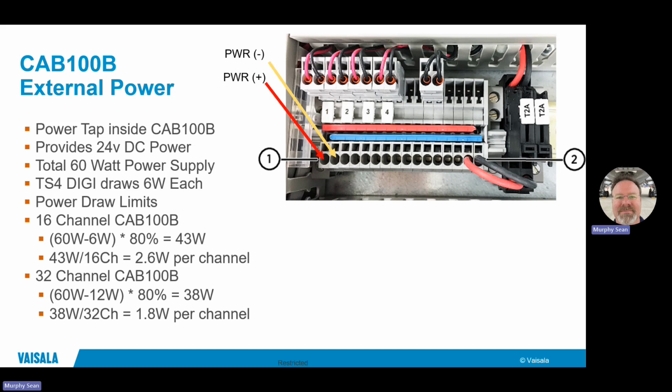The terminals have a pattern to them. On the bottom strip, you can see where I had labeled power plus and power minus. That pattern repeats across that entire bar on the bottom. The bus bars that are above it, the red one connects all the positives together, and the blue connects all the negatives together. So essentially, this acts as a giant power block.